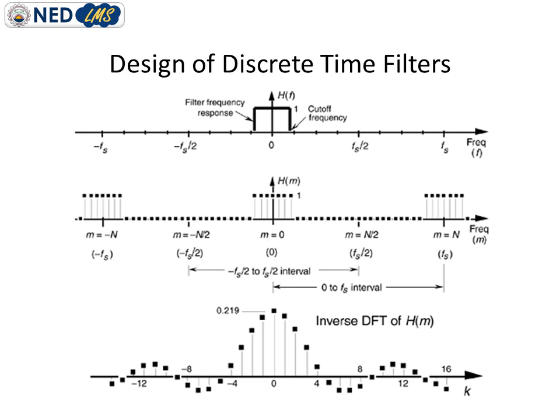once this impulse response is obtained, we can easily extract the coefficients which can be utilized to design the filter. Actually, the magnitude of each discrete line represents one filter coefficient.